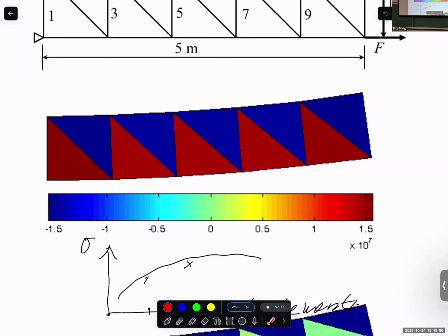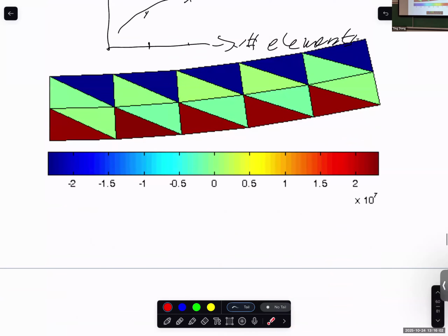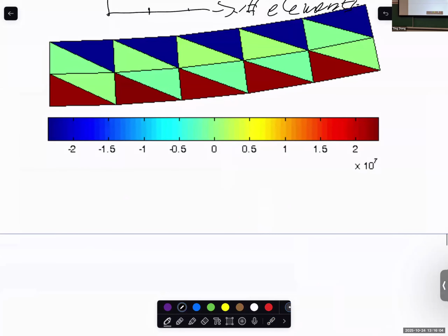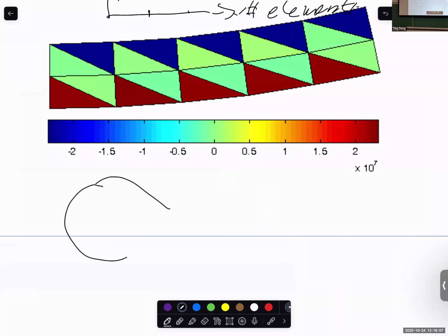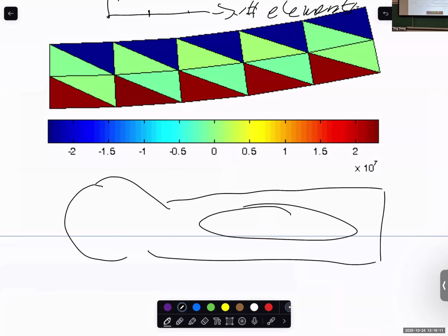And also, let's say if you have a complicated structure, they allow you to do the partition. Some of you may have seen a torque arm design like this, and there's a hole here, and it's complicated geometry. If you do mesh, they may have really weird triangular or quadrilateral elements, and at some angles they are really distorted and cannot give you good results.